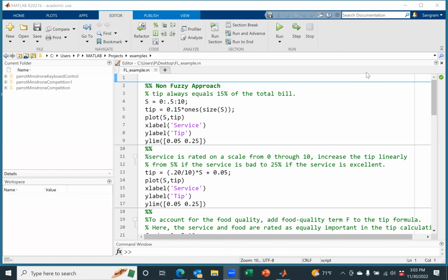In last class, we talked about a very simple toy example for fuzzy logic. But fuzzy logic, if used properly, can be used to control robots. As a matter of fact, when I worked on the Bell 609 project, we used fuzzy logic for sensor fusion, and it worked very well. It was certified, and that code is still used in the Bell 609 air data altitude heading reference system.